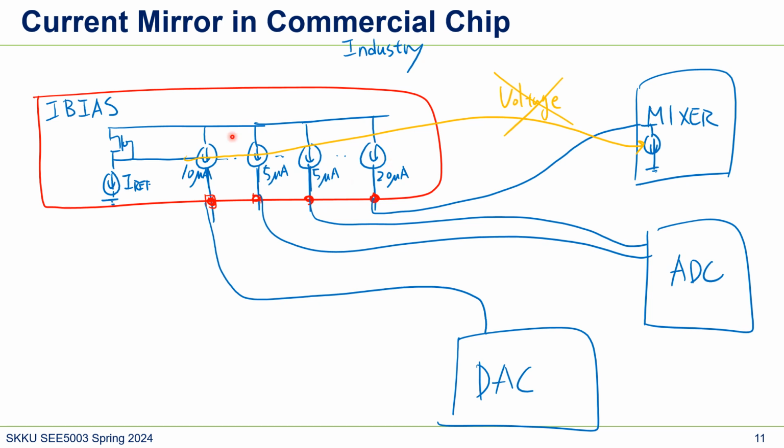The distance is important because to make this current mirror, what we learned is their current ratio is decided by this ratio, right? And also VTH or mu n Cox, or mu p Cox for PMOS. So these variables are important, and they should be aligned between these branches. And these variations are a strong function of distance.